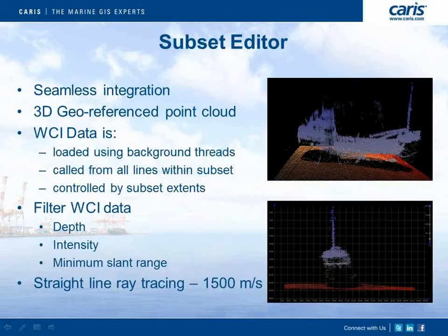In Subset Editor, again, seamless integration is the big highlight about water column data. The learning curve for users is almost non-existent. When the data is loaded in Subset Editor, you'll end up with a 3D georeference point cloud that displays with your bathymetric data. The data is loaded using background threads, so you can continue to use Subset while data loads.